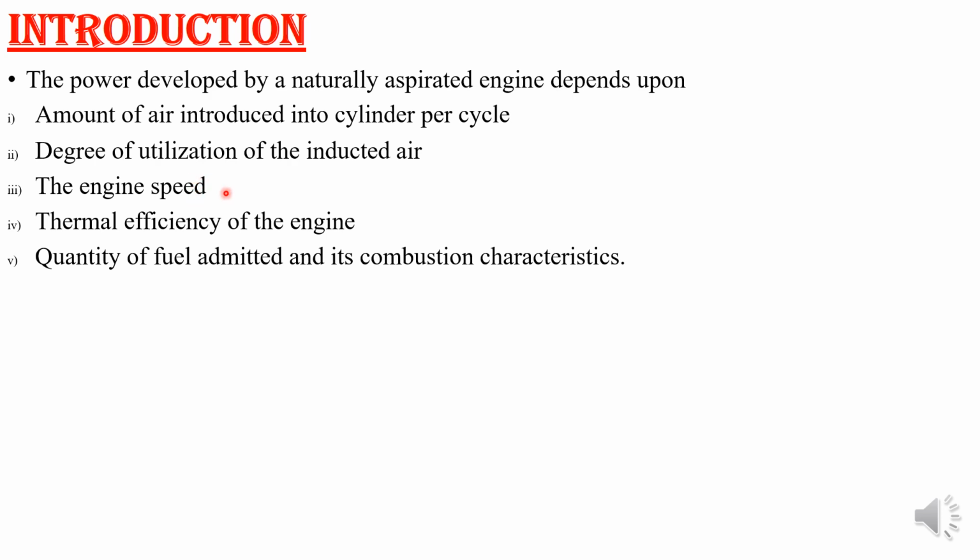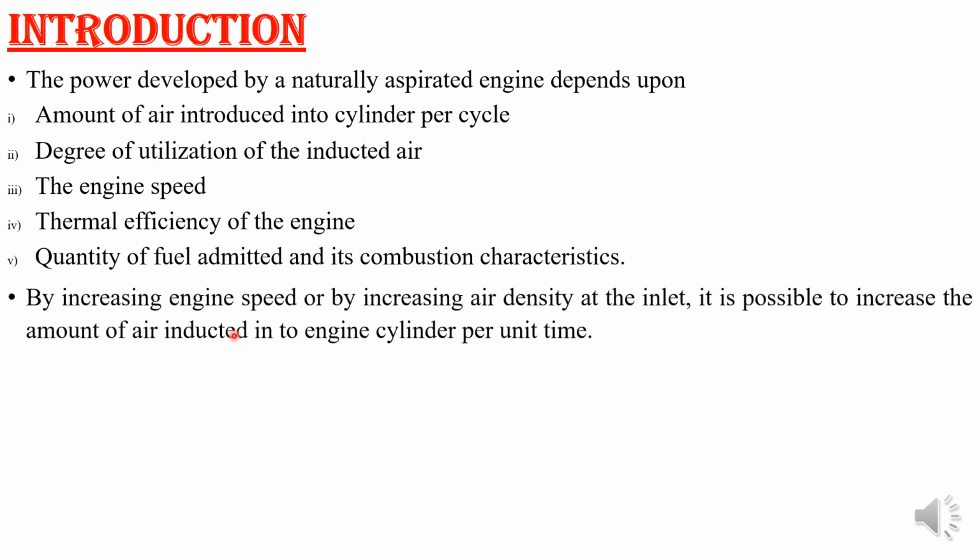Thermal efficiency and quantity of fuel also depend upon the thermal stress of the engine materials or the thermal load, and it is difficult to change these after a certain limit. Hence we can change the amount of air, or the engine speed can be increased. By doing that, we can increase the power output of the engine.